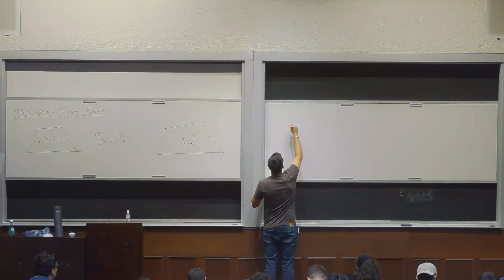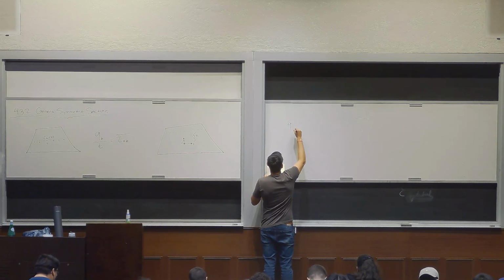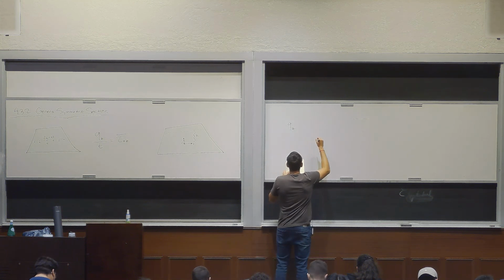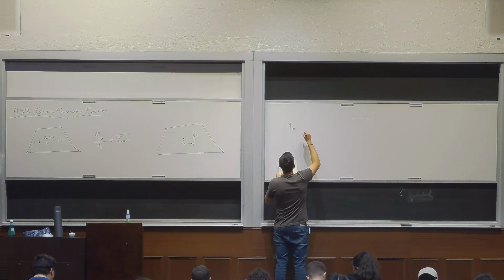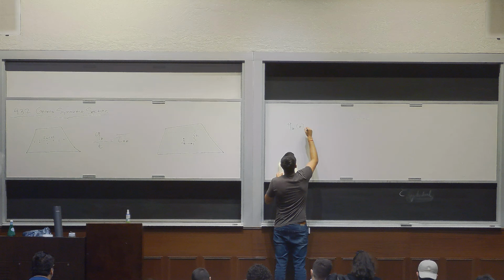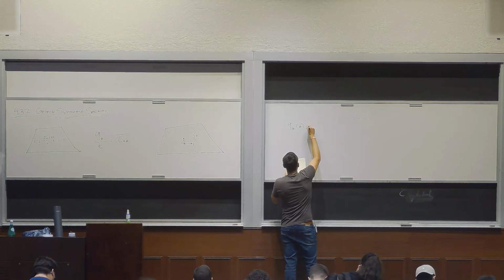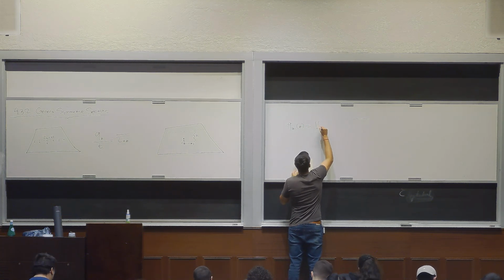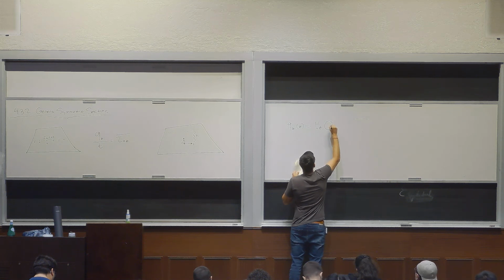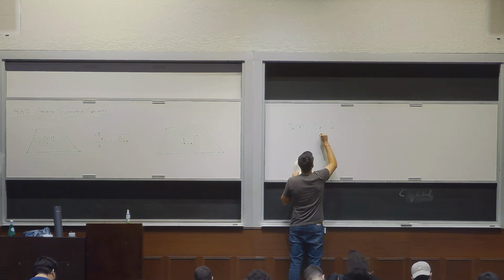So the shear flow, it's the same thing, right? You have to just divide by the thickness at that location. QZ, as a function of z, is going to be Vz times big Q over Iy.